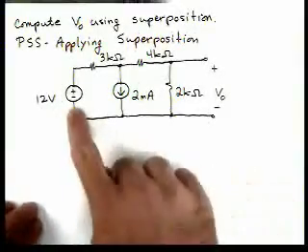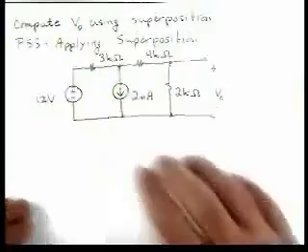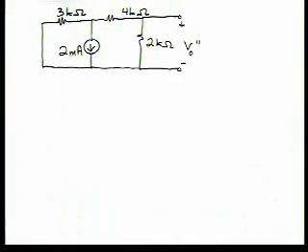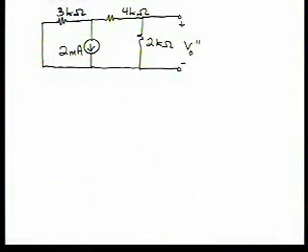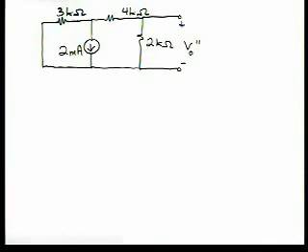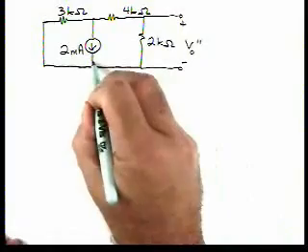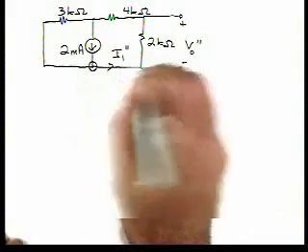Now we're going to deactivate the voltage source and turn on the current source. When we turn this voltage source to 0, that's going to be like a short circuit. So our resulting circuit is here, and we can see the voltage source was over here. We turned it down to 0, so that's characteristic of a short circuit. To start off, first we're going to apply current division, and we're going to calculate this current, which I'll call I1 double prime.